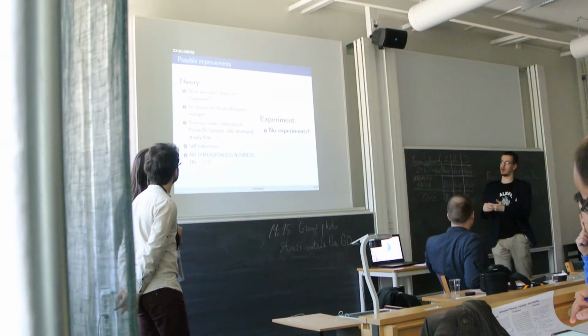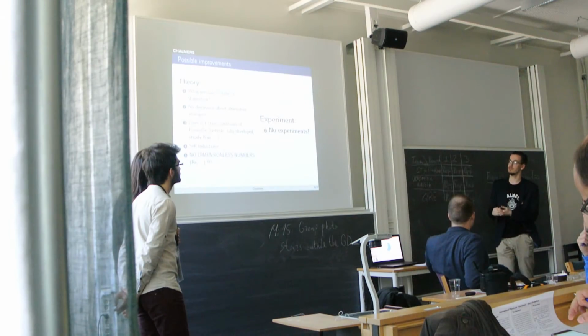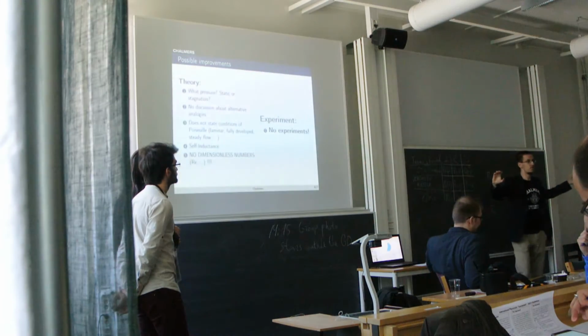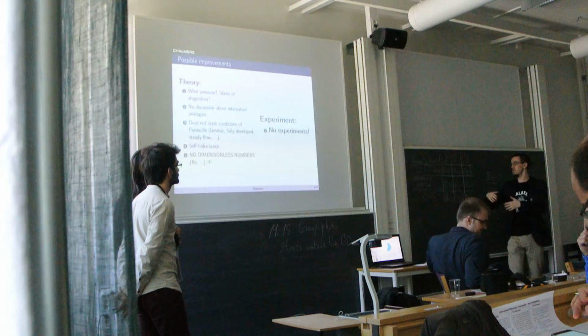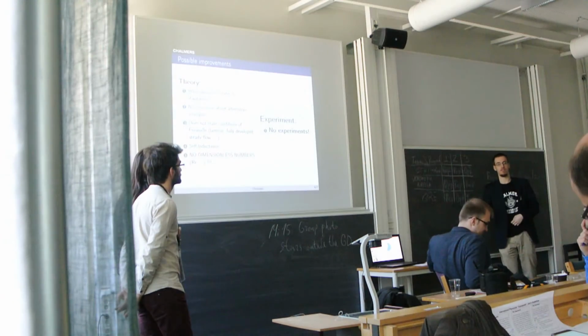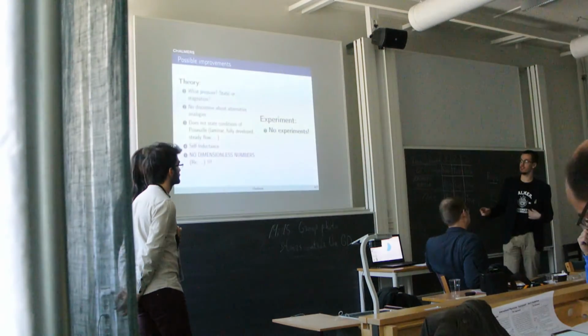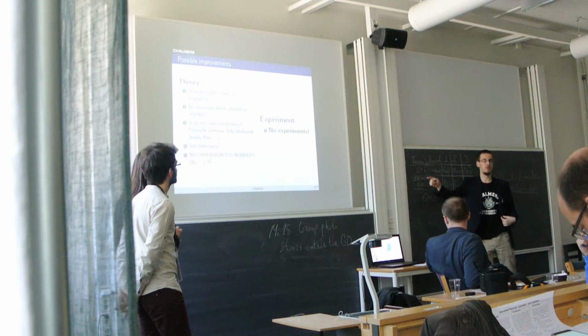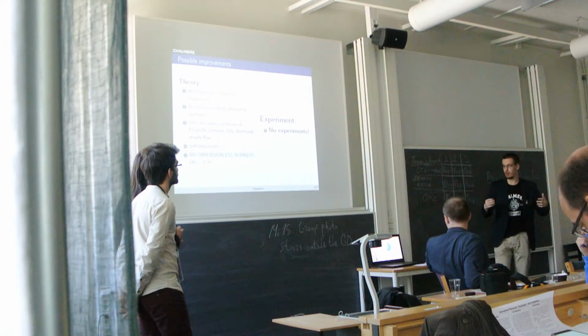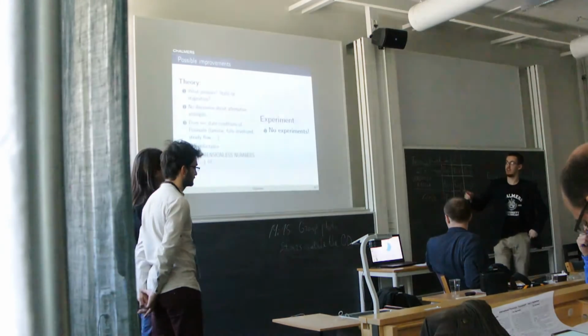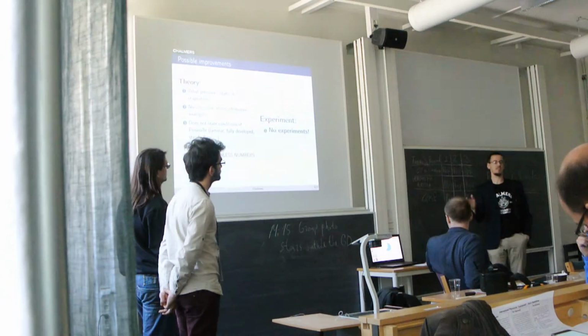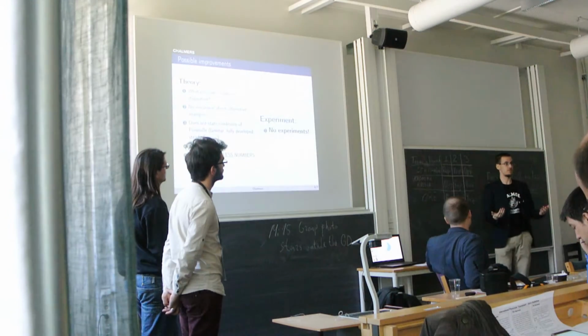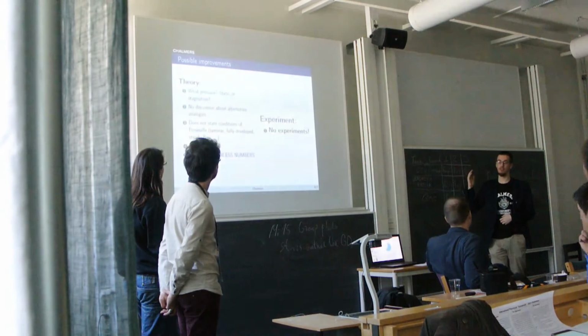For example, Poiseuille requires laminar, fully developed flow in a straight tube. You only said that it holds, and later you specified cylindrical flows. But what's really important here is the laminar flow, because the question asks what the limits are, and laminar flow is limited, or at least indicated, by the Reynolds number, of which I saw no mention.